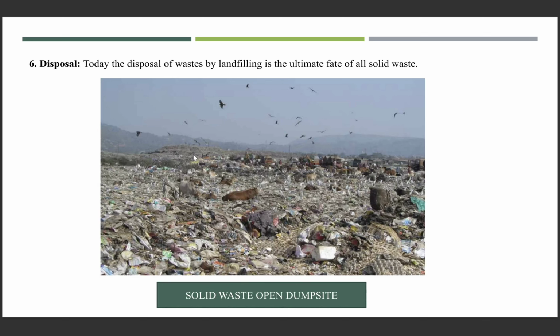So last is the disposal. Disposal of solid waste is at the bottom priority of all the methods of managing solid waste in integrated solid waste management. In our country, earlier there was no separate collection of wet and dry solid waste, and this mixed waste is very difficult to manage, and eventually it used to end up in landfills, and attract a lot of animals, rodents, and pathogens.